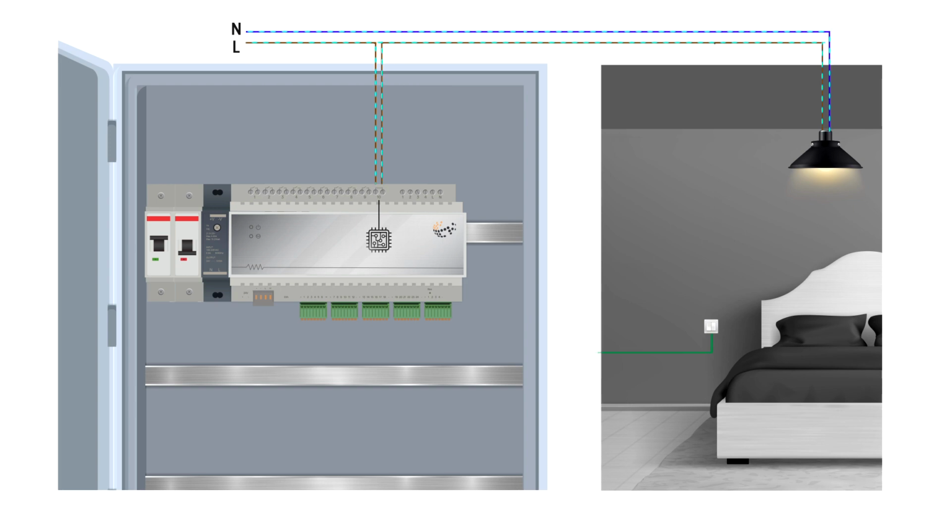The wall switch is connected to the controller, and upon receiving a signal from it, the controller sends a command to the relay, closing the circuit and turning on the lights, allowing you to control lighting in a familiar way. Light and motion sensors are also connected to the controller, enabling the automation of lighting based on their readings. The system decides whether to turn the lights on or off depending on the sensor data.